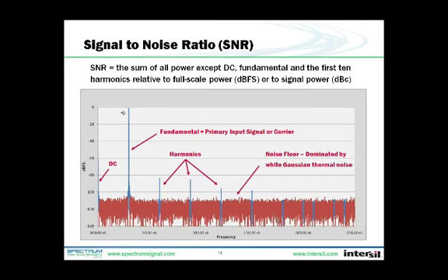An ADC's SNR is set primarily by 4 factors: quantization noise, which comes from the number of output bits; thermal noise, which comes from the ADC's input. The ADC will have higher order harmonics due to DNL errors, or just periodic errors in the output, and there will also be clock jitter noise. The first 3 are set by the ADC's design, and those are relatively fixed. It's important to know that the jitter noise is influenced by external factors, and those include the clock jitter, the input frequency, and the input amplitude. So next, let's look at the effects of jitter in a little more detail.